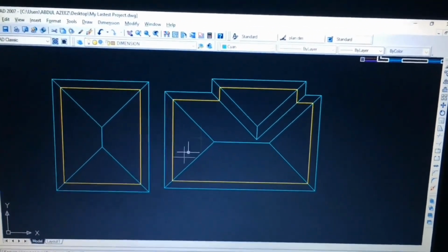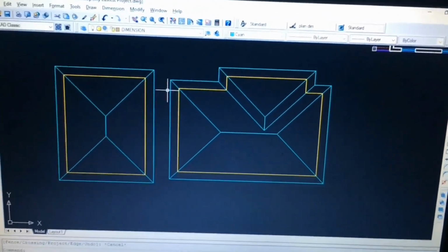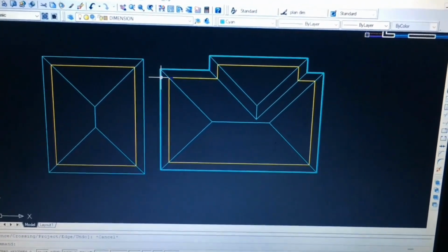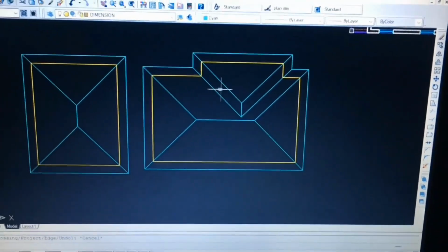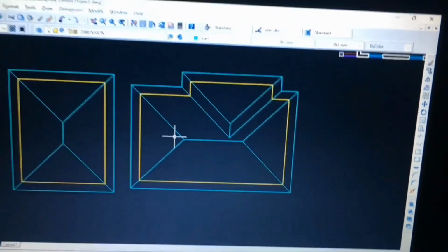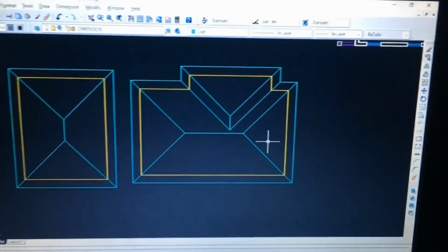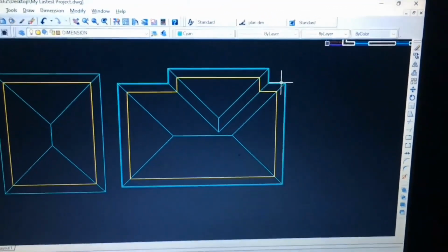What I did here, I used mirror, then use copy selection to transfer the small line to the other edges of the same direction. Then I use the fillet, the line, and the trim and extend the modify tools.